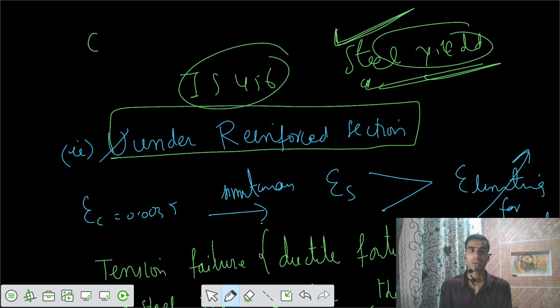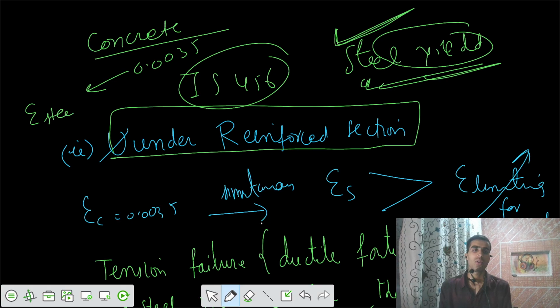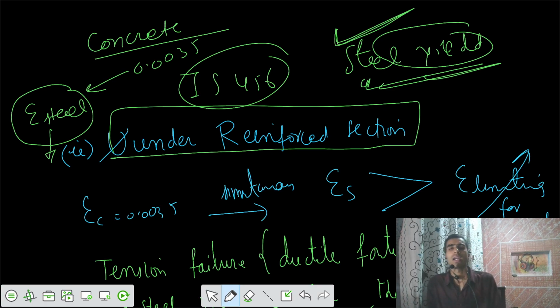Concrete is in its intact position and is not going to fail as strains increase up to 0.0035. At that time, the strain in steel was such that the steel was already yielding, so we have not kept the steel underutilized when the concrete has crushed.